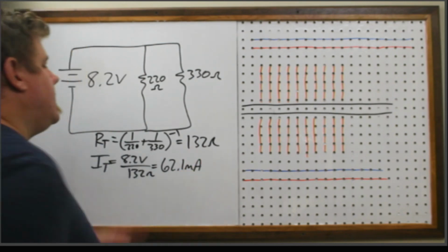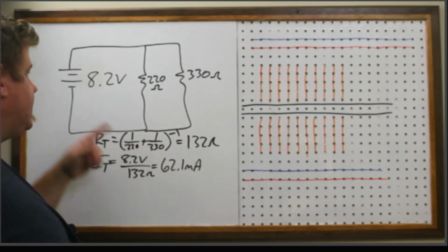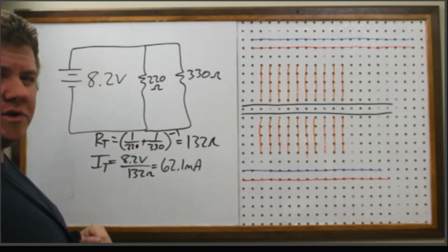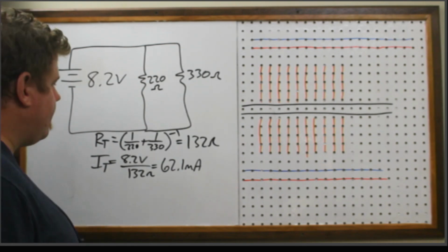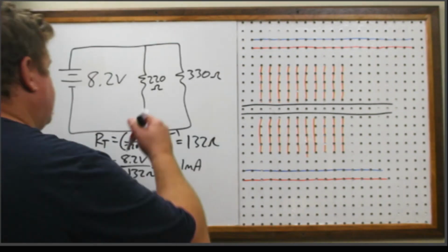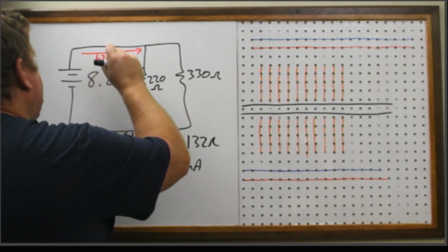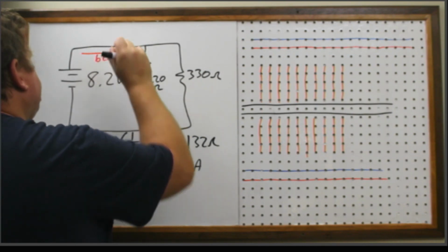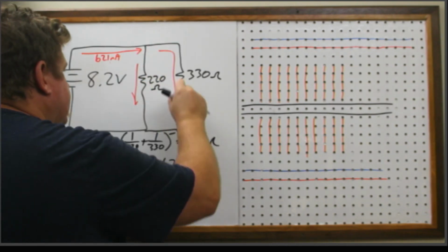Okay. So in the series circuit, we had what? 920 ohms. That's a lot more resistance against that battery versus just 132 ohms total. It's like roughly 1/9 or something like that, 1/8. So anyway, I expect a total current of 62.1 milliamps coming into that first node out of the source. Okay, so that means now I have to find each of these currents.